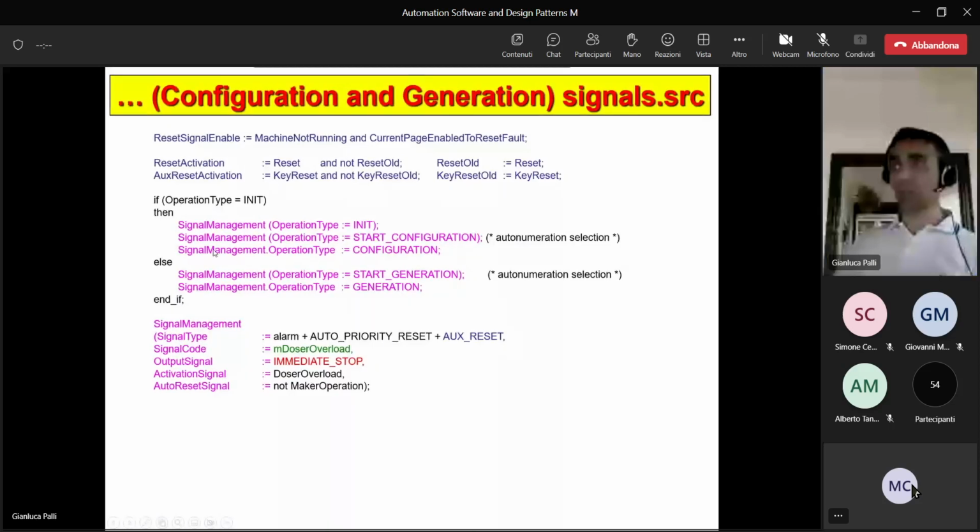Then when you call again the signal management function block, the operation type is configuration if the machine is in the init phase. So it means from this configuration, the signal management function block will read the type of the signal, eventually other configurations that are needed, and this will be stored in the memory, the configuration memory. Then this is repeated for all the signals.